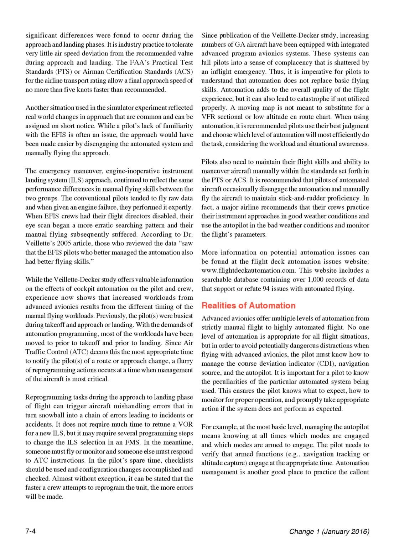Previously, the pilots were busiest during takeoff and approach or landing. With the demands of automation programming, most of the workloads have been moved to prior to takeoff and prior to landing. Since Air Traffic Control, ATC, deems this the most appropriate time to notify the pilots of a route or approach change, a flurry of reprogramming actions occurs at a time when management of the aircraft is most critical. Reprogramming tasks during the approach to landing phase of flight can trigger aircraft mishandling errors that in turn snowball into a chain of errors leading to incidents or accidents.